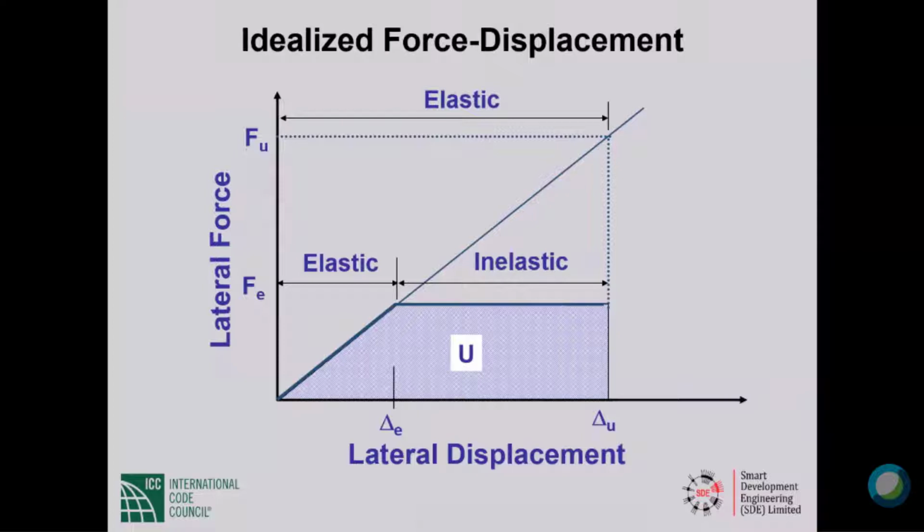No residual displacement, meaning no damage to be repaired. Now, this elastically responding structure develops a force F sub u in the process of responding to the earthquake and suffers a total displacement of capital delta sub u.